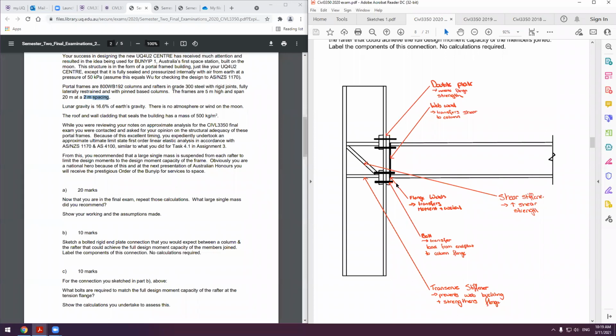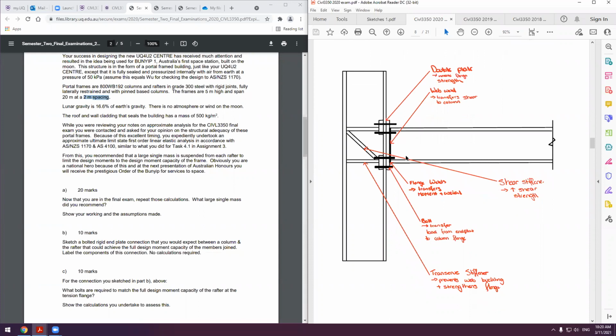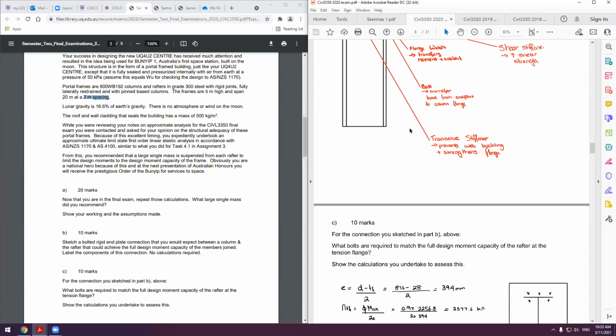Make sure you have the bolts in the flange, which transfer all of our loading, and then also our web weld onto our end plate, which is then bolted into our connection. If anyone has any questions about this connection, let me know, but it's what I was shown, and I've just transferred that through for the last couple of years and it seems to be what's correct.